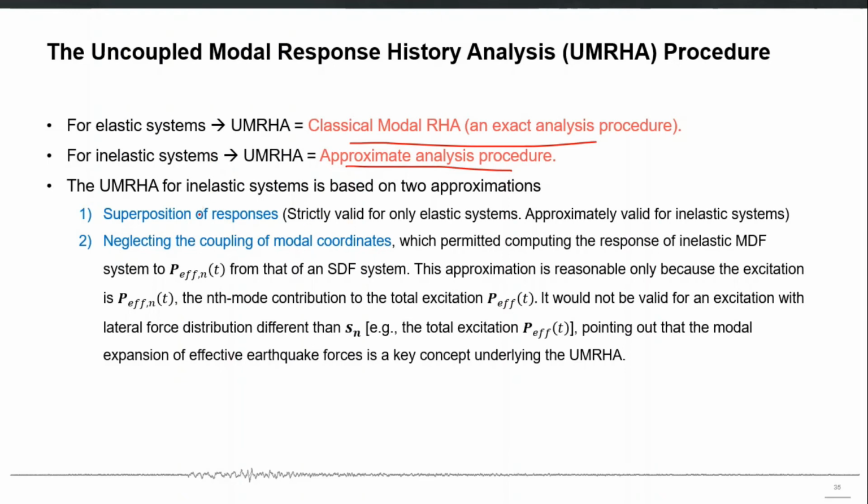One is that the responses of each mode can be combined, superposition. This is strictly valid only for linear, elastic systems. It is not valid for inelastic systems, but still we use that. The second assumption is neglecting the coupling of modal coordinates, which permits us to compute the response of an inelastic multiple degree of freedom system to the nth mode effective earthquake forces using just a single degree of freedom system of that mode only.